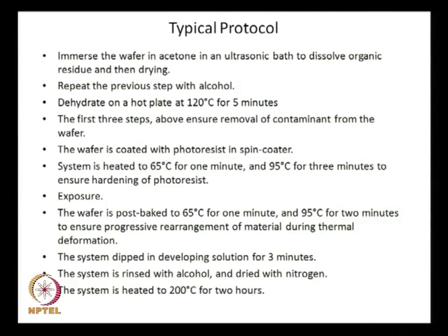The system is rinsed with alcohol and dried with nitrogen. The system is heated to 200 degree centigrade for 2 hours. Again, with this 200 degree centigrade for 2 hours, you ensure that all the rearrangements are done, completed, frozen.